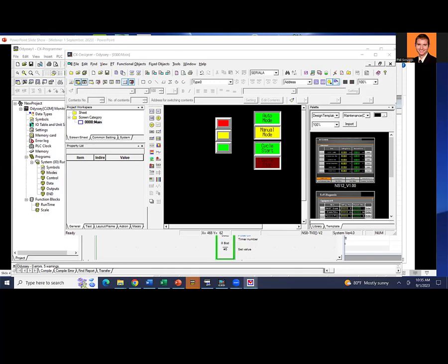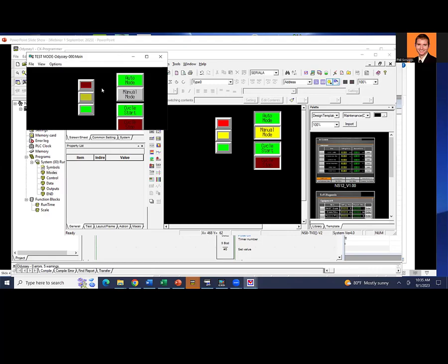And there it is. It actually opened on a different screen, but there it is. So this is the actual running software here. If I want to go into manual mode, I would have to do a cycle stop. There we go. I'm cycle stopped. This is one of my basic lessons I do whenever I teach PLCs, right? If you're in auto mode, but not in auto cycle, go ahead and blink this light. It gives students an opportunity to create some timers and things like that. Then you can go into manual mode. And if I go into manual mode, light the yellow stack light.